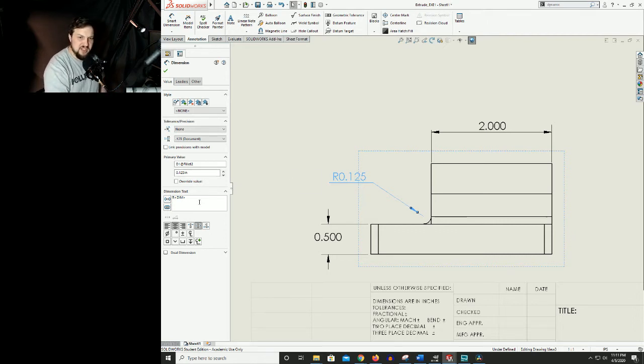So what we're going to do is we're going to click in that box. We're going to hit enter. Turn on your caps lock because all of the words on all prints are always capitalized. We don't do any lowercase stuff on prints. That goes for title blocks, it goes for notes, it goes for just text that's on them, it goes for our initials when we check them. Everything is always uppercase. We do not use lowercase on these. That is drilled into your head day one back in the days of hand drafting. And now it's even easier because we have a caps lock tool and we're not doing this stuff by hand.